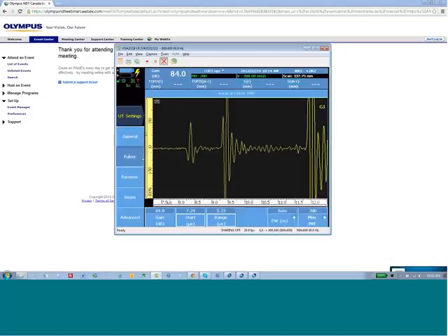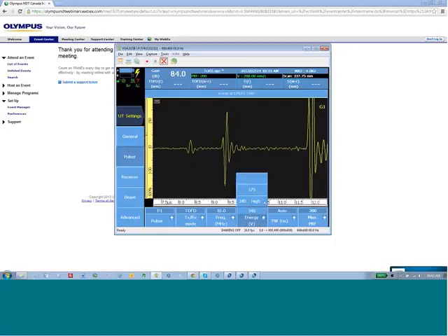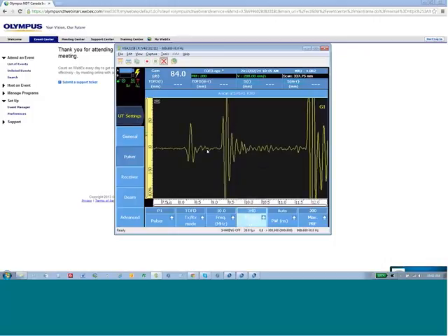Our pulsar, the frequency was automatically selected during the wizard process. We will use one of the 3 available voltages for what works best, paying attention to the signal to noise ratio. The pulse width was automatically set. The PRF, which is managed blind to the user or can be controlled manually, optimizes now the TOFD group inside of a multi-group inspection with phased array.